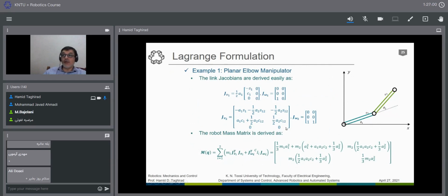We have a full vector here because this is a 2 by 2 matrix as well. We have the last part here, but all of them are equal to 0 because we are in a planar case and we don't use that in our cases. Now we have the JVs and J omegas found. Very simply go to this vector, MI, JVI transpose, JVI, omega I, IC transpose. And this can be done by just simple matrix manipulation.